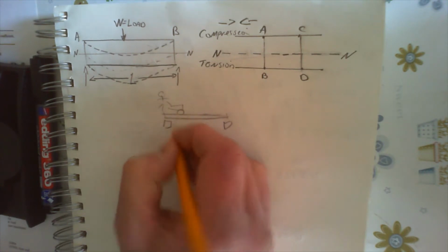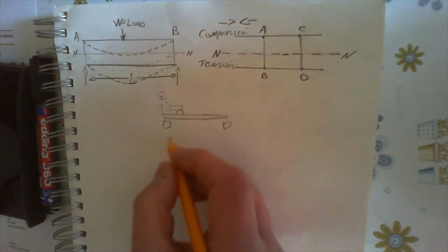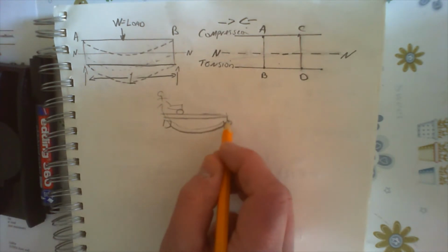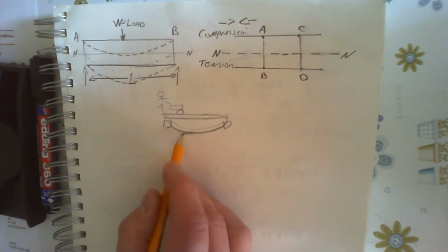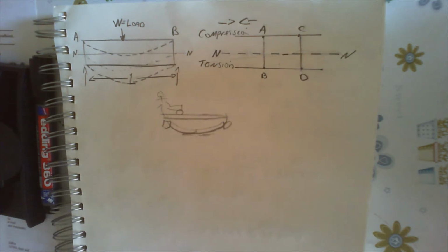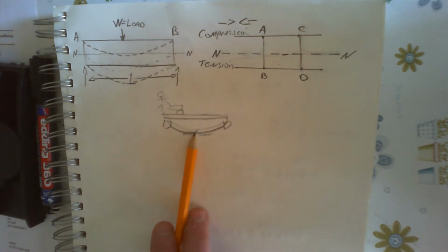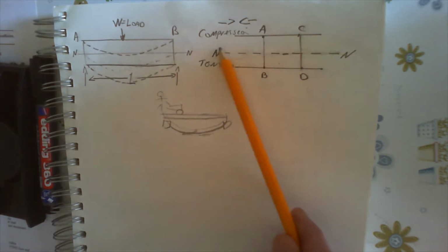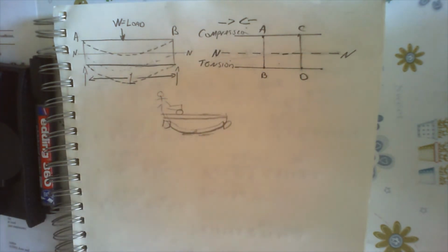That will sag dramatically, and what tends to happen is at the bottom, the tension will rip the fibres apart, and it will fail when that occurs. That separation of fibres and failure will occur before any effect on the neutral axis. In other words, the material will fail before you can see the neutral axis change. Anyway, that's a wee footnote.